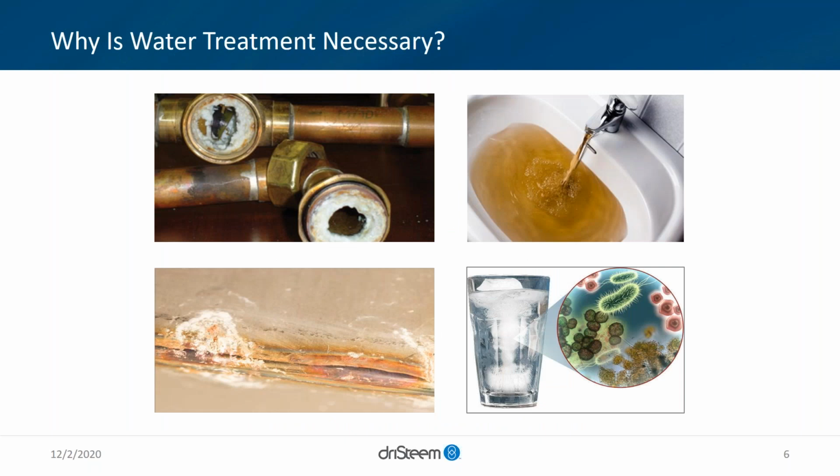So why is water treatment necessary? We touched on this in the very beginning. The top left picture is scale forming in this pipe. If we decrease that pipe diameter with all that scale, do we really think that our system is going to be performing to its utmost maximum capacity? Probably not. We're going to get increased velocities there and obviously scale, things that we don't want.